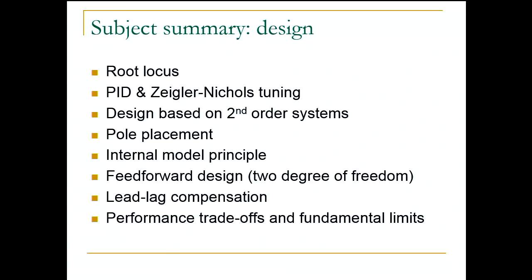And then we said, if you can place the poles of the closed loop in certain locations, then you can address certain specifications on performance for the closed loop system. And we saw also that the second-order system is often used as a rule of thumb for higher-order systems if you can ensure that the two second-order system poles are dominant poles.